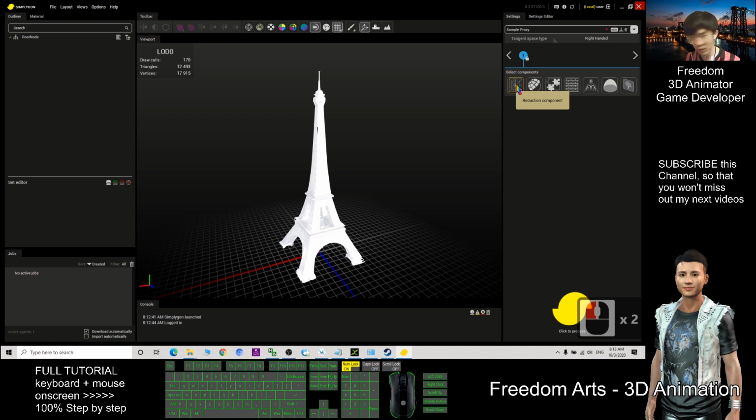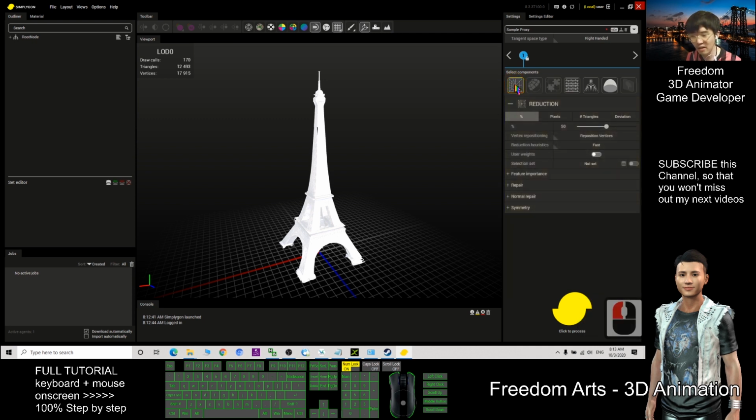Then click the reduction component to turn it on. Click the triangles to limit it to 5000. We don't want a high poly mesh. We limit it to 5000 triangles. Next, click the material baking component.